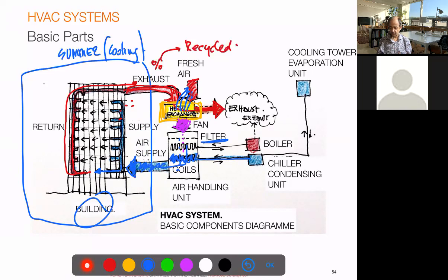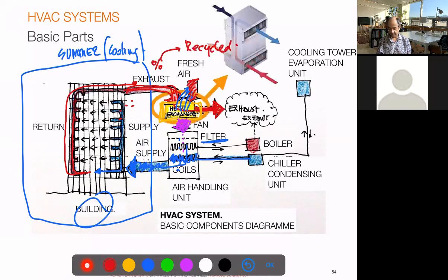And of course, this is cooled by a set of two pipes, right? After you cool the air, the fluid is hotter, so it goes to the chiller, the cooler, and it becomes cooled back. So this is a closed circuit, continuous cooling. And this goes to the chiller, in which you will have two units, a condenser inside and an evaporator on the roof usually, or on the exterior. You know, the cooler is always a set of two, and they need a lot of space.